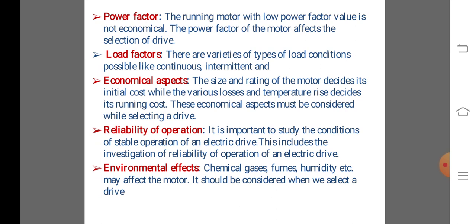We have to watch where the motor can be placed, and the surroundings must maintain room temperature, apart from chemical gases, fumes, humidity, etc. Because those harmful things may affect the motor, we must be careful to place the motor in a harmless, free space. It should be considered when we select a drive.